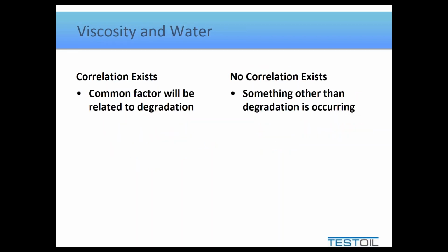Now, comparing these tests, again, we look for the correlation and ask ourselves, well, what is going on here? So similarly to acid number, water content will accelerate degradation. So that's where we're thinking the common factor is. If both viscosity and water content are changing together, we're probably going to experience more degradation. If they're not, then something other than degradation will be occurring.